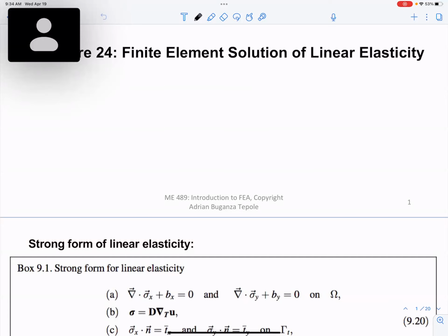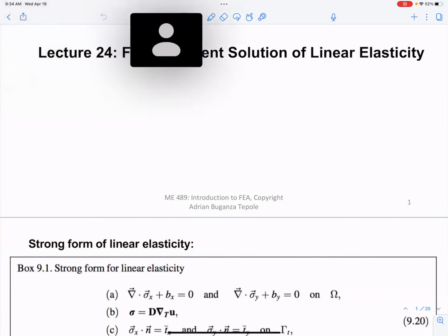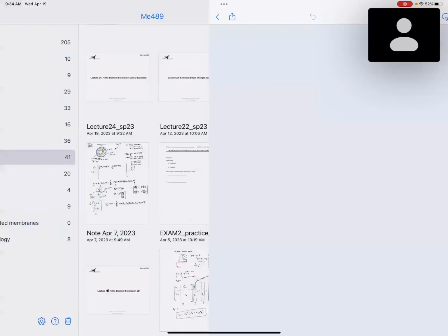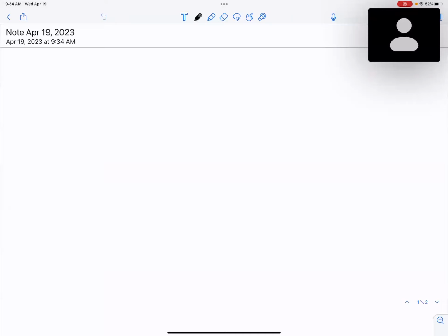I actually want to say something about the Abaqus exam. How did it go? Okay, not okay. I'd say one thing, because I don't think anybody did it this way. You were free to do however you want, but the easiest way of setting up the problem was with symmetric boundary conditions, and do an eighth of the model. It's fine if you didn't do it like that, but the easiest way of doing this type of problem is to do that.